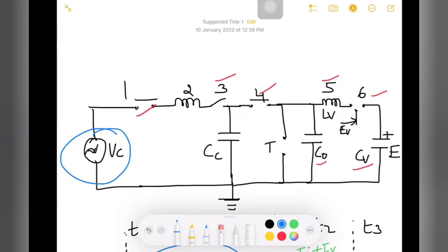When the auxiliary circuit breaker 4 and the test breaker T, these two, are closed, the closing and making switch S1 causes the current to flow through the circuit. Whenever I close this from the first circuit breaker, the current will flow through the circuit.